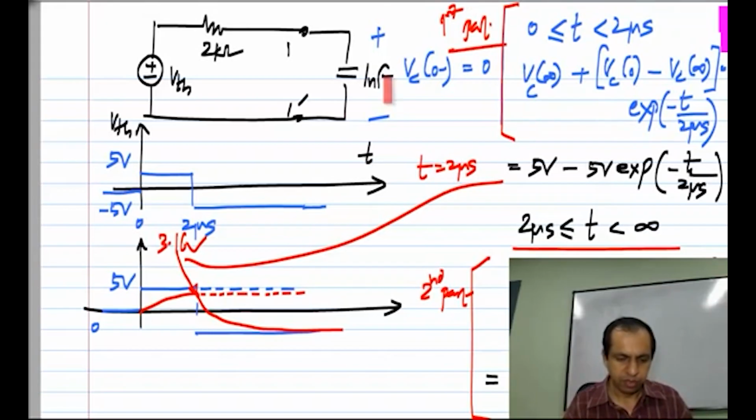Okay. So in a similar way, you could have a network with many resistors, many independent sources whose values are stepping from one constant to another, or you could have fixed voltages and currents with some switches being operated. When you change the states of switches, what can happen is that it can effectively look like a step input, and sometimes when you change the states of switches, even the time constants can change. Okay. So you have to be aware of all of these things.